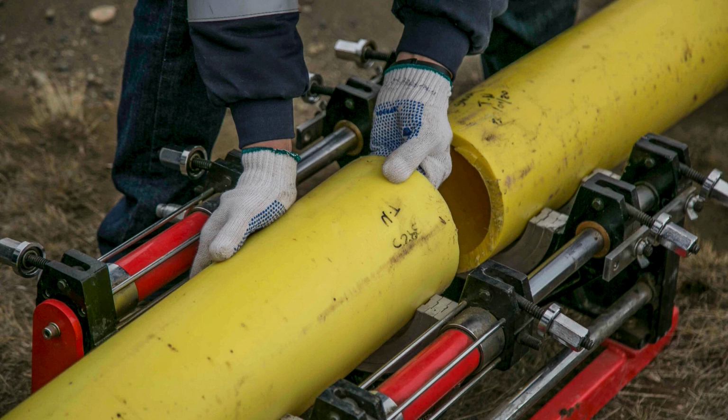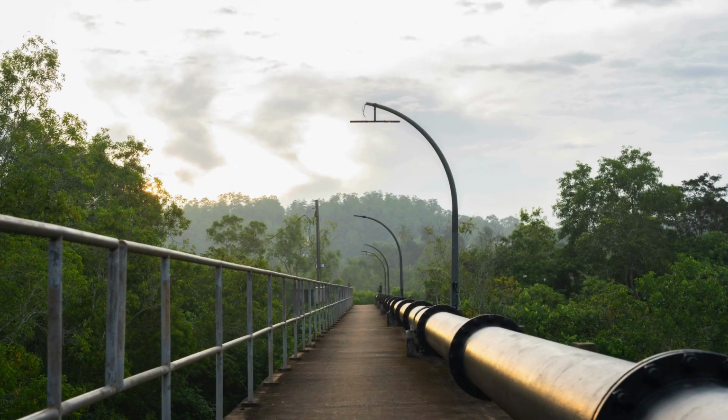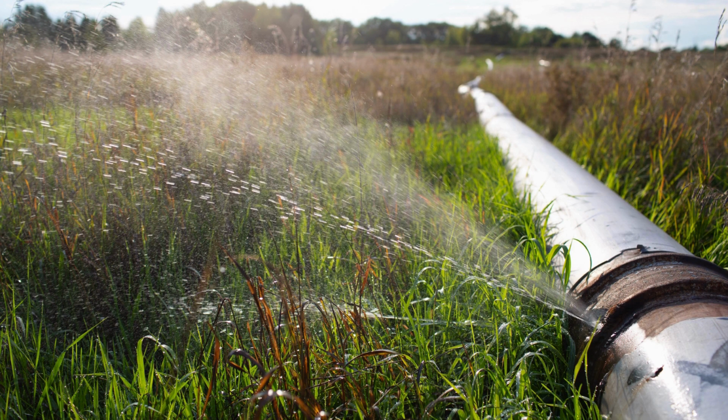Although the axial shortening is small for a single pipe section, it can become significant when many pipe segments are connected in series, since the contraction accumulates. This cumulative shortening can place additional forces on pipe joints. If the joints are restrained, these forces may lead to separation, excessive stress, or even joint failure.